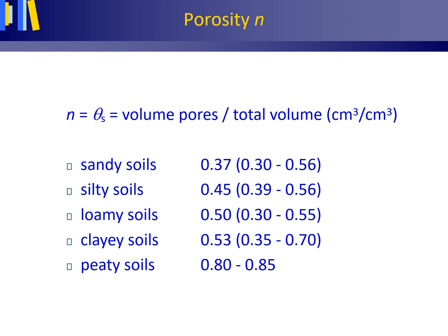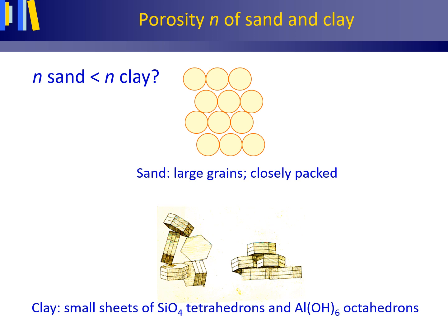The soil's ability to retain water is strongly related to particle size and pore size. Water molecules hold more tightly to the fine particles and pores in a clay soil than to the coarser particles and pores of a sand, especially a well-sorted sand, so clays generally retain more water. The average porosity N for sand is lower than for clay. Sand has large grains that are closely packed, and in a well-sorted sand, one predominant pore size due to the predominant grain size is shown here.